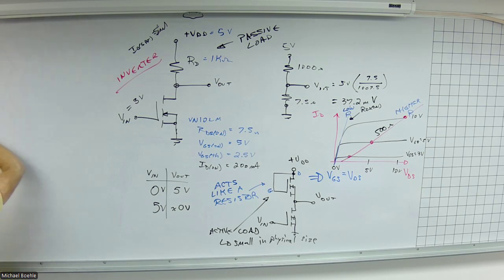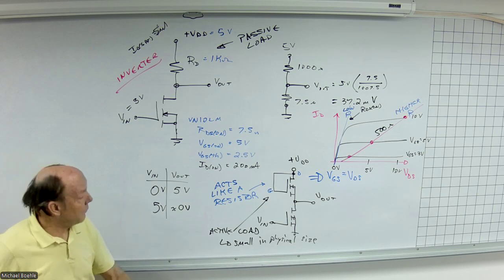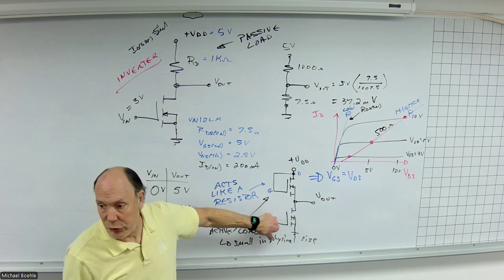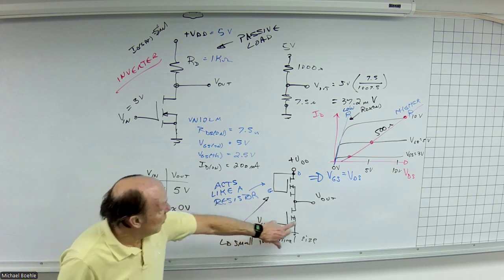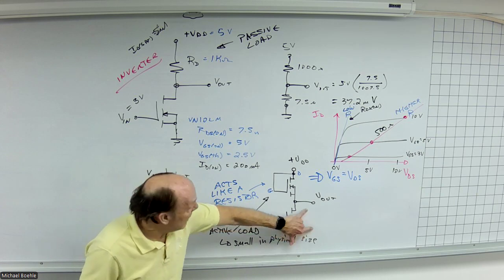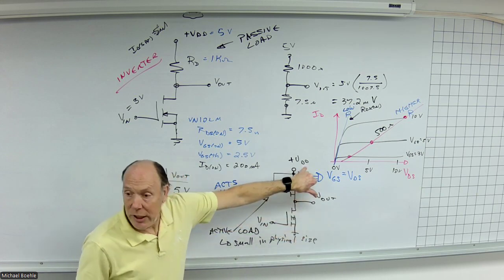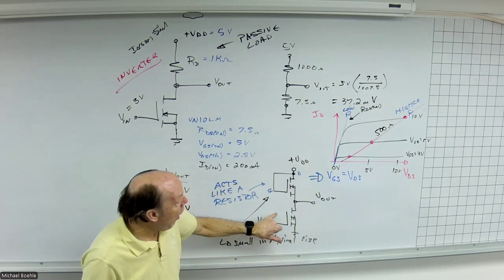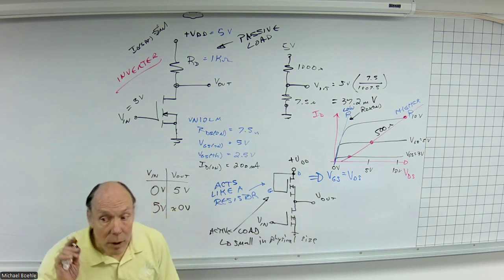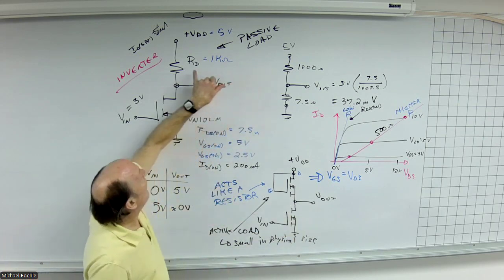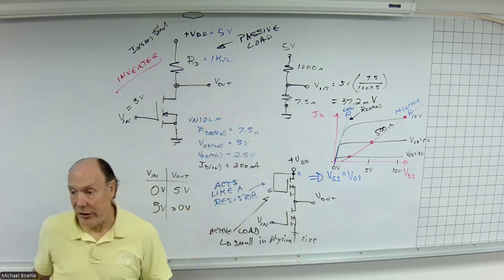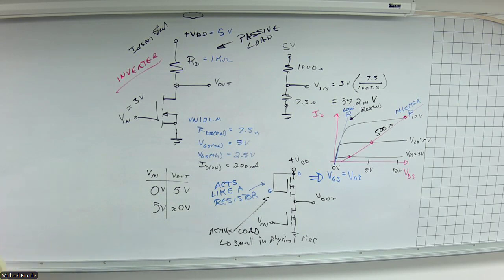Signal lower. That acts as a resistor also. No, the lower MOSFET is still a switch. This is still acting like a switch. So when it's off, this acts like an open. I still see the drain voltage coming out. When it's on, it's still a voltage divider. You replaced it. So I replaced a component with a MOSFET that is acting like a resistance. The lower transistor I didn't do anything with. That is still my switch.